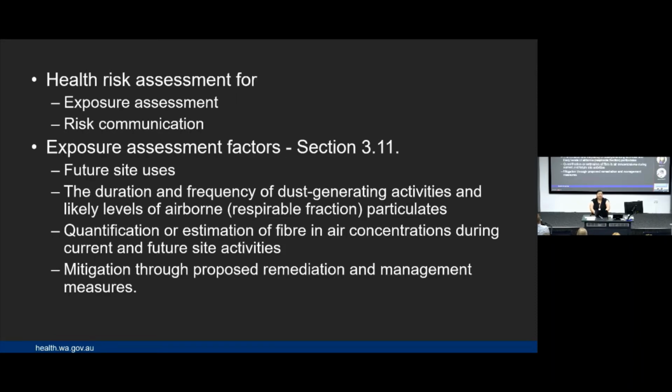Now, as I mentioned, usually at that point, 90% of sites end there. You found asbestos, you found it above the criteria, and you're going to remediate and manage it. And that's a perfectly acceptable solution to make with asbestos because it is a controlled substance and we're trying to eradicate it from the environment. So unlike other substances, very rarely would you go to a health risk assessment stage because it's a controlled and banned substance, so you're going to have to manage it anyway.